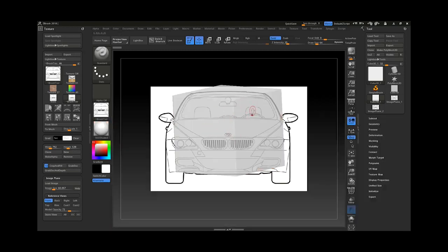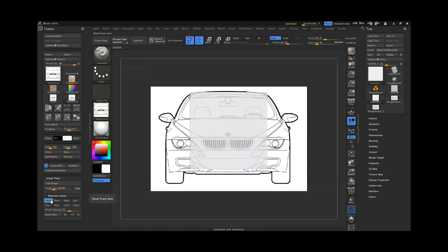Okay, anyway, if I want to come back to my original position, the only thing I need to do is double click or one click on the front, and as you can see, it's going to be to the front once again. And of course, remember, perspective gives you another view. So when you have things like these cars, you need to turn the perspective off.